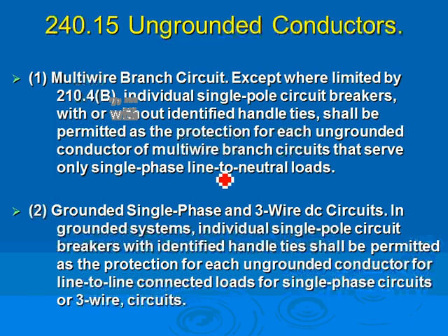Or you can also use them with a DC system, 3-wire DC circuits in a grounded system. An individual single-pole circuit breaker with an approved handle is permitted to protect the ungrounded conductor for line-to-line or line-to-neutral loads in a DC 3-wire circuit.